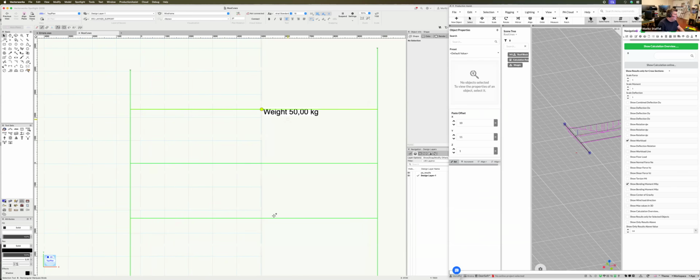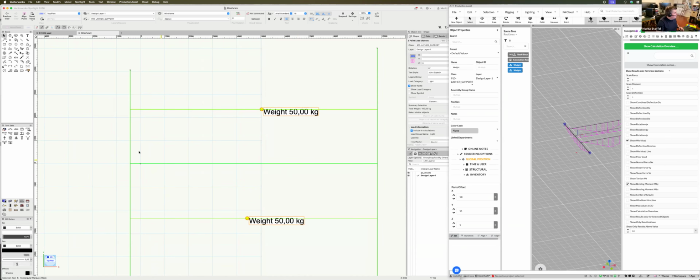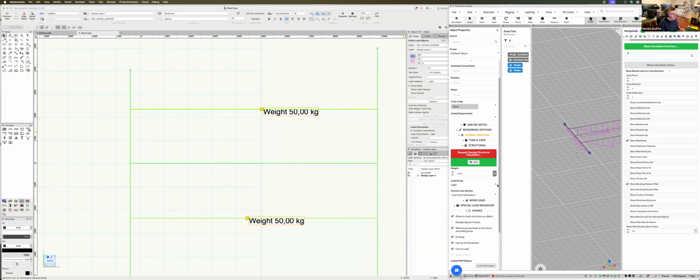If you now add also a load here, you will see it increase a little bit on the side. Now, if you increase this a little bit more, we don't want the pounds, we want the kilos. We go to like 200 pounds. You see at some point it will change the display and the way the loads are calculated, and give you an indication of how much load on each individual beam is used and how much capacity is used.